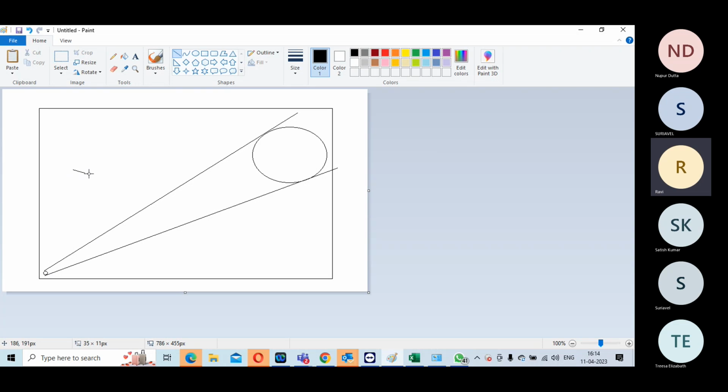If the mux is sitting somewhere far off like this, or the mux is sitting here, then this is like deviation. Your clock tree won't be of good quality. This mux should actually sit over here. Then the construction will happen in a good manner to get your minimal insertion delay. However, the clock shouldn't go away from this side. Correct. It should not go like this.